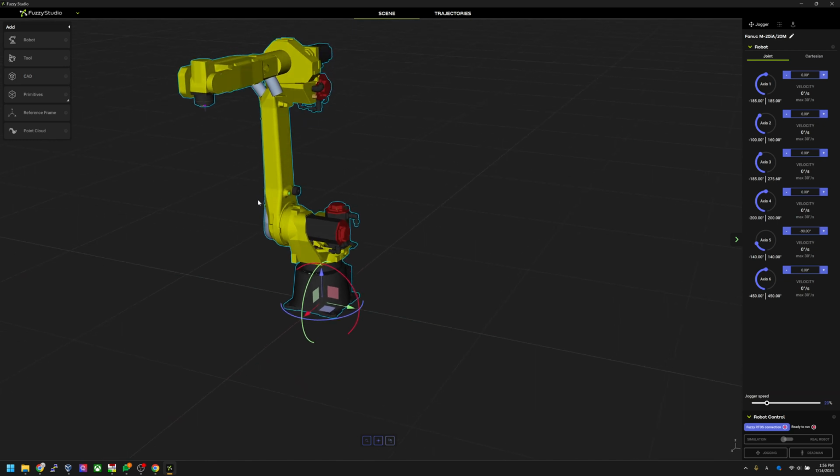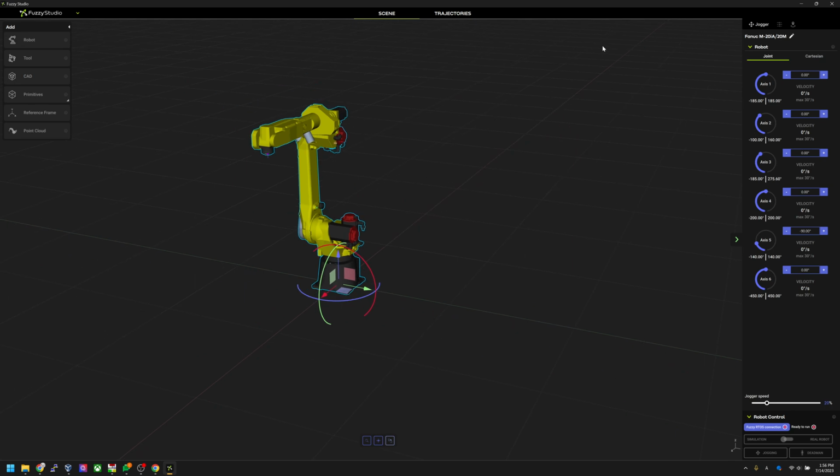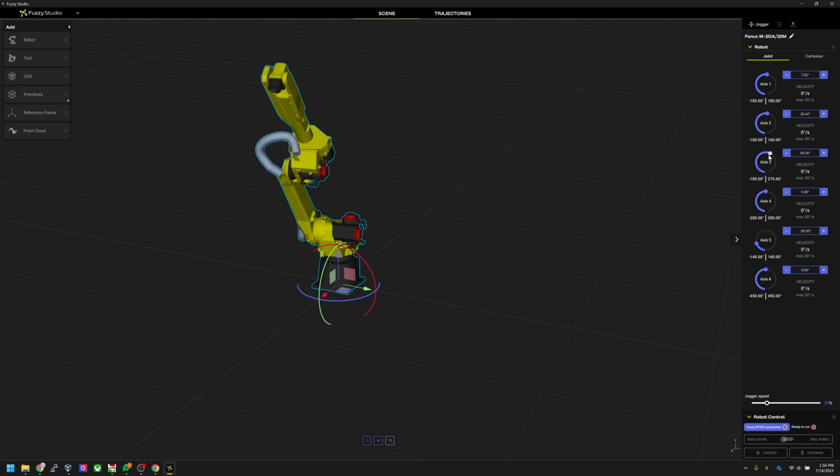The first thing is to show you how to operate the robot. Before that, on the right hand side, you see the jog panel. This panel is for jogging the robot on each axis. For example, here is a rotate panel. For axis 1, I can just press here, and then I can rotate axis 1. Just do the same for the other axes. You see? It's very easy.